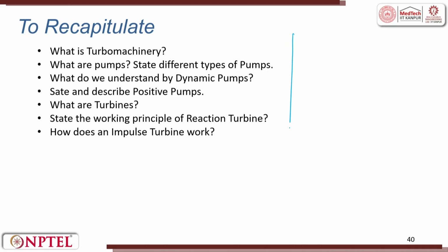To recap, in this lecture we saw what are turbomachines, what are pumps, their classifications, what is a dynamic pump, what is a positive displacement pump, what are turbines, and different types of turbines, that is reaction turbine and impulse turbine. This is a very important topic, because when you see any electrical system, you will see there is a pump or there will be a motor. So, you will now onwards start appreciating how these pumps and motors work and how they are making our life easy.